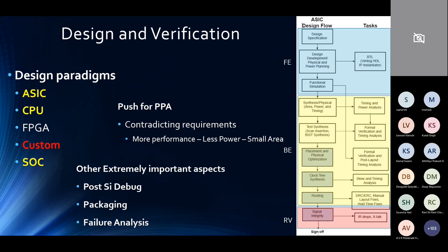And then the last one is called RV, or reliability verification. So you can design a chip, but you have to make sure that it's reliable. It adheres to a certain standard in terms of the number of years it has to work at a certain spec frequency and things like that. So no matter what you are designing, you will see this design methodology in place.